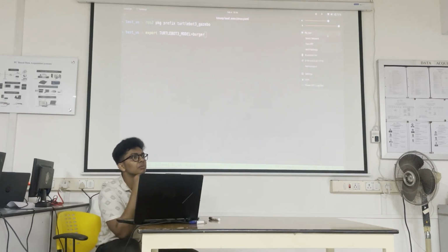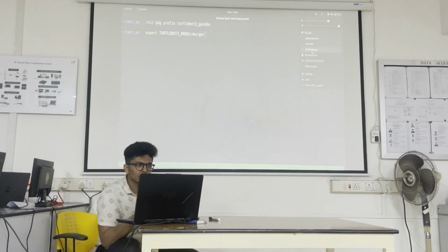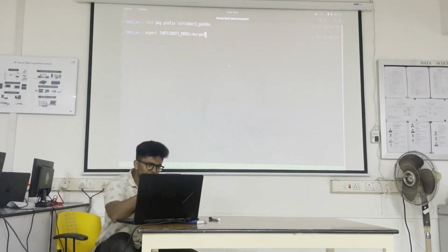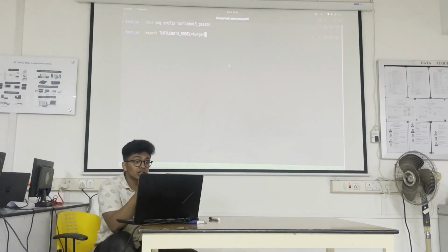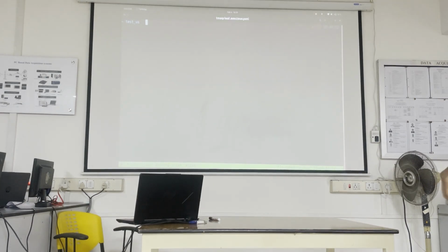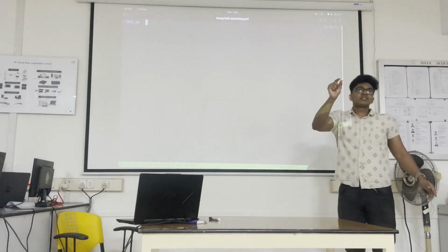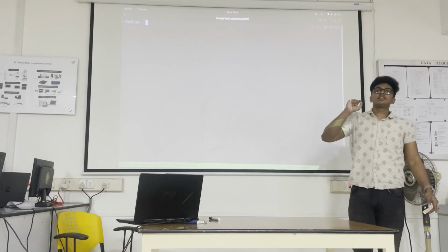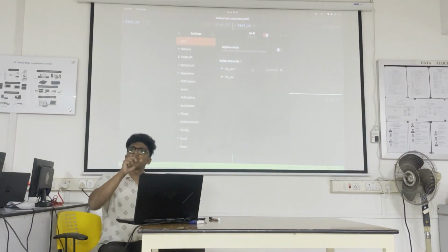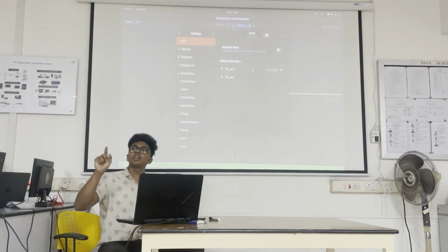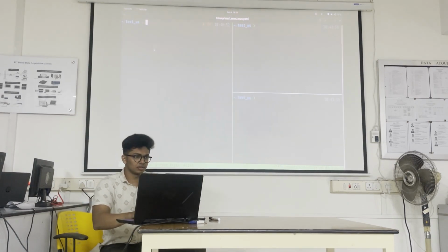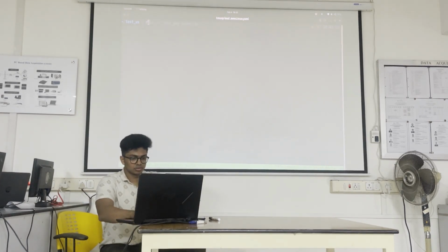Did the installation complete? Did you source ROS? Yeah. So package not found. Did you type turtlebot3_gazebo? Guys, install one more package as well. You all installed turtlebot3, right? Just add hyphen gazebo to that and install that as well: ros-humble-turtlebot3-gazebo.